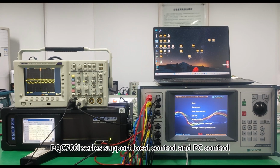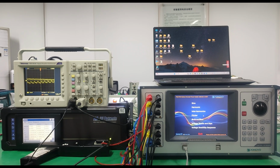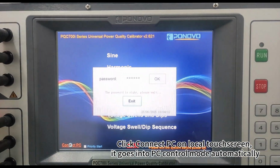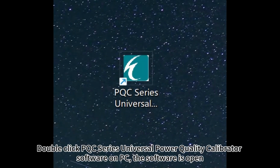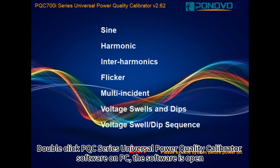PQC700i series support locally control and PC control. Use an Ethernet cable, one end is inserted to Ethernet port, the other end connects to PC. Click Connect PC on local touchscreen, it goes into PC control mode automatically. Double-click PQC Series Universal Power Quality Calibrator software on PC, the software is open.